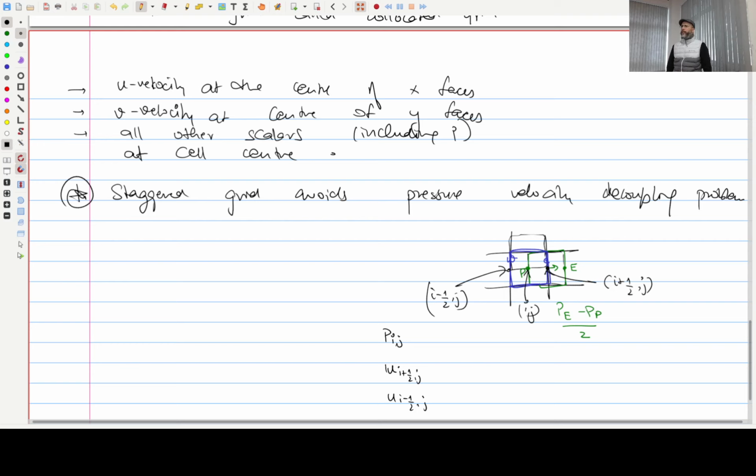So we use all kinds of least squares methods and so on that you can learn in an advanced course in CFD. But for now, the idea to take away is that a staggered grid allows us to avoid this. Since we would want to have some practice of using a staggered grid, the implicit methods that we'll propose will be discussed in light of staggered grids. But they can very well be applied to collocated grids as well with the same idea. The implicit ideas are not different. It's just that we are getting some practice in using this staggering, because staggering is a bit more complex than collocated grids when working out the equations.